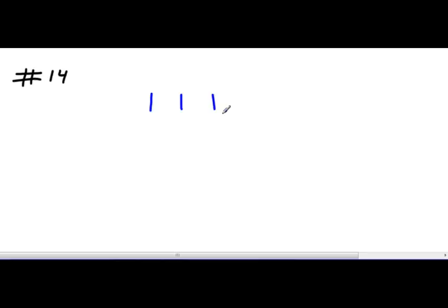It's flip-flop, flip-flop, flip-flop. Well, look at it. See, where is the set? Is the set inverted? No, it's not inverted. Is it high? Yes, it's high. So this thing's setting all the time. Even if it changes to something else, it's going to set immediately. Look at the reset. If you have 1, 1, 1 going into the NAND gate, what do you have going out? A 0. So is it resetting? No, it's not resetting. So it's 1, 1, 1 all the time. The clock happens. It doesn't matter. It's still 1, 1, 1. The clock happens. It's still 1, 1, 1.